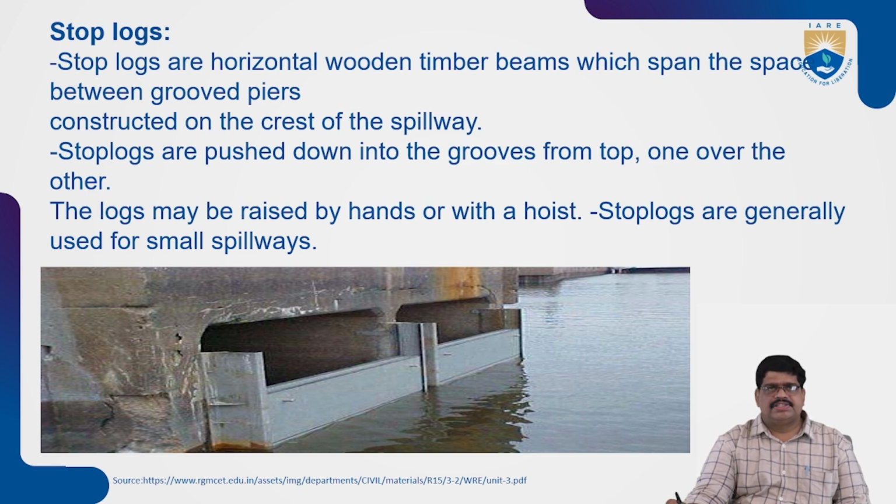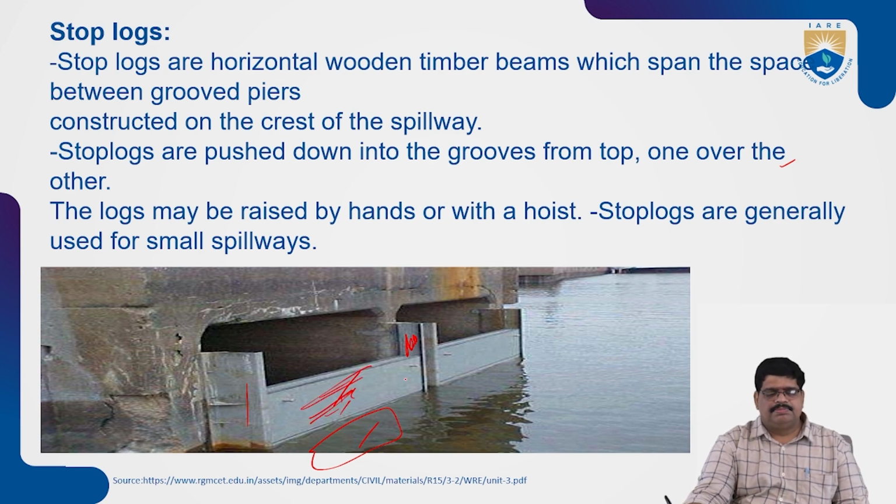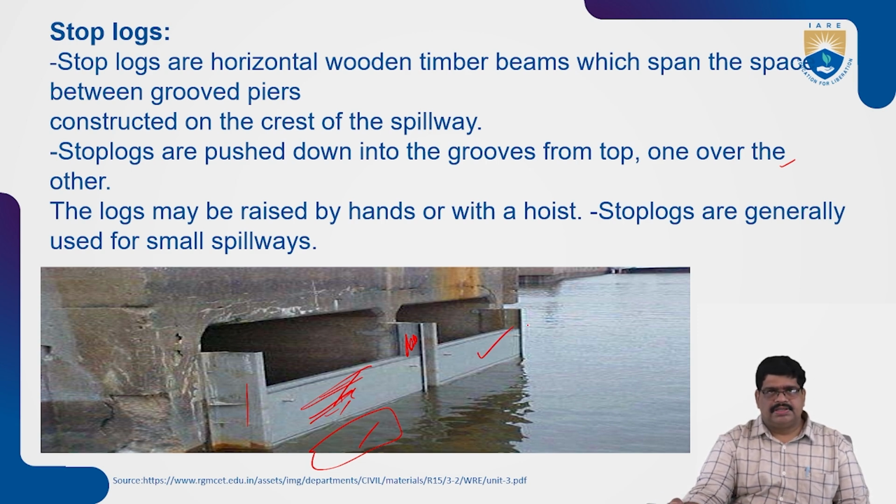Construction of the crest of the spillways, and stop logs are dropped down into the grooves from the top, one over the other. In these grooves we have to provide the stops, and wooden stop logs can be provided in these grooves.